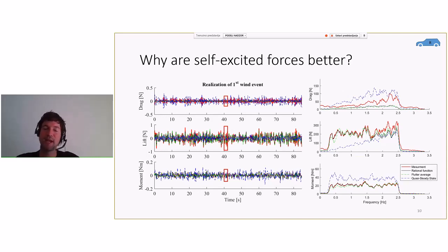And you might say this is perhaps conservative, more conservative, less conservative. Essentially, it's not really important how you think in this perspective, but it's simply not a suitable model to represent the actual damping. So having less damping on the structure is actually dangerous because you're under-designing your bridge. Having more damping on the structure is also not cheap to build a bridge. So it's good to have representative models. And definitely these flutter derivatives present a very good accuracy.